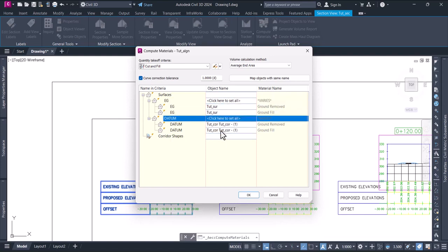corridor. Okay, actually when it is in fill, the top of your road is the reference surface to calculate, but in the cut, if the top of your road is used to calculate the volume, then it is actually wrong. So you have to create another surface as well, which links to the bottom. That I will show you in a later video. For this video, let's keep it simple, and we just select these surfaces to compare with and say okay.